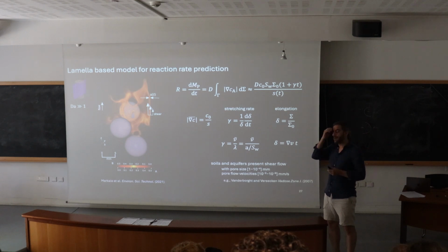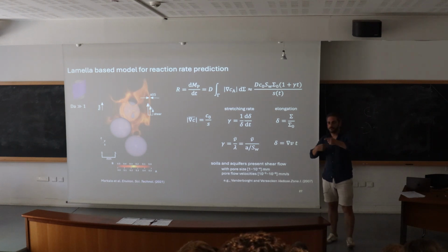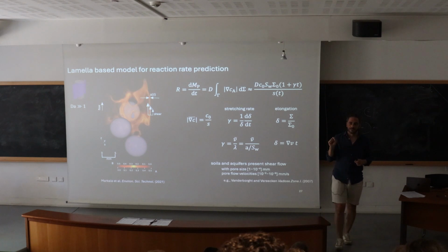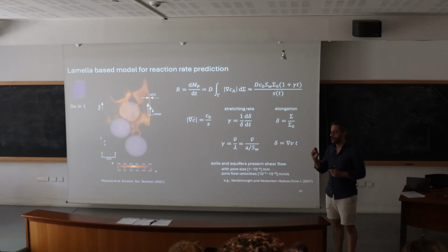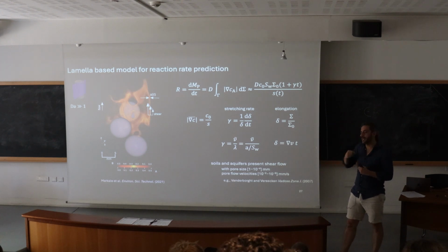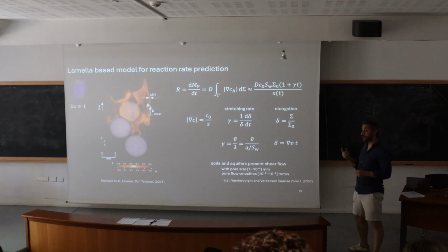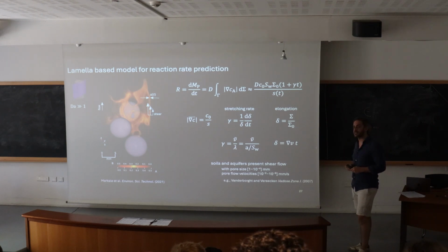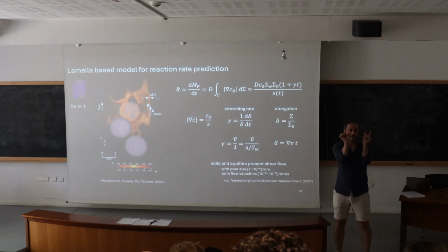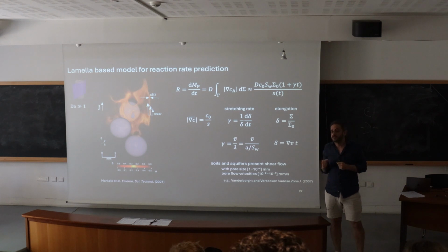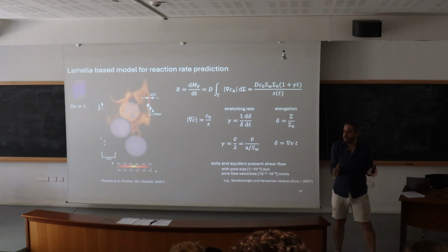There is, and that was demonstrated by Amir Raouf and Majid Hassanizadeh, that when you go below a certain threshold of saturation, it's related to the correlation of velocities. Even with the classical formulation, at very low saturations, dispersivity starts to be smaller and smaller. So dispersivity grows until a certain threshold, but after that it goes back down. It's because of the velocities within the system. If you desaturate a lot, at the end you have few pipes, few regions that control the flow, and that's all. Then you cannot disperse a lot. You don't have too many stagnation zones. You have mainly preferential paths at very low saturation.